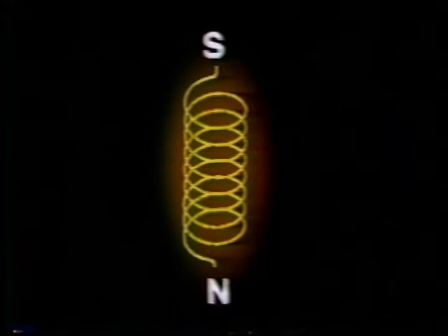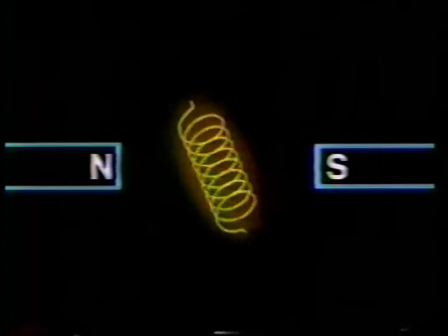We have seen that when a current passes through a coil, a magnetic field is produced. An alternating current will cause the north and south poles of the field to rapidly exchange positions. If the coil is placed between two permanent magnets, its changing magnetic field interacts with the permanent magnets, causing the coil to spin. Electrical energy has now been converted into rotational mechanical energy. Reversing the process, that is, turning the coil mechanically, produces electricity, and you now have a generator.